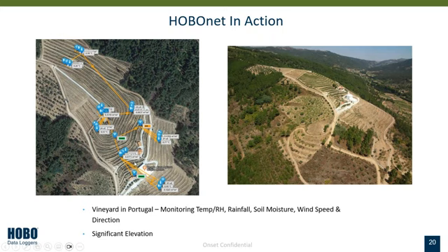So it can handle elevation, and it's all dependent. You have to get these up off the ground. Ground is definitely a killer for 900 megahertz technology, but if you can get them up off the ground 6+ feet, and if you're doing elevation, maybe you angle them slightly, most likely we can handle some of these areas or larger areas that you want to put this technology in, and do it at an affordable cost.